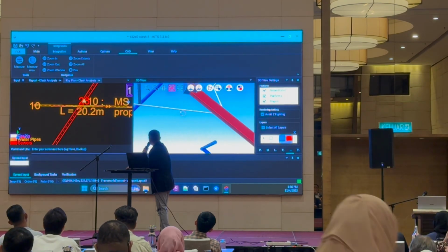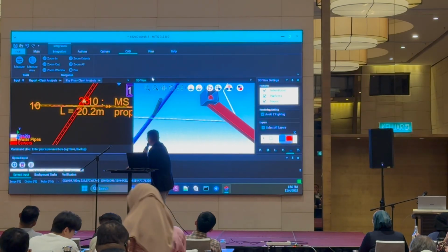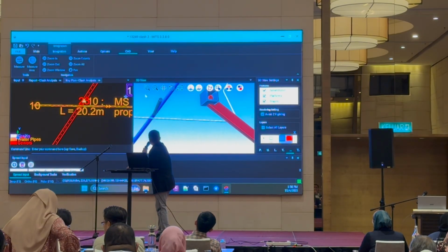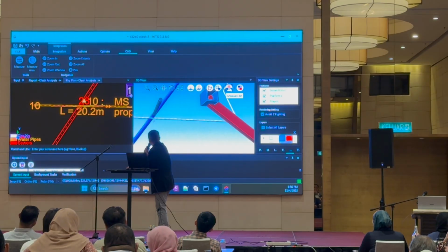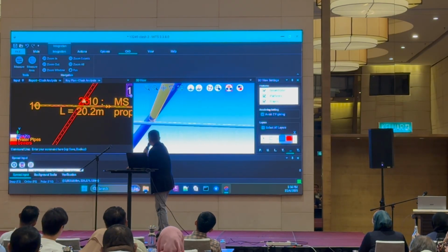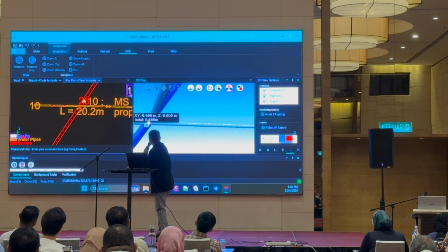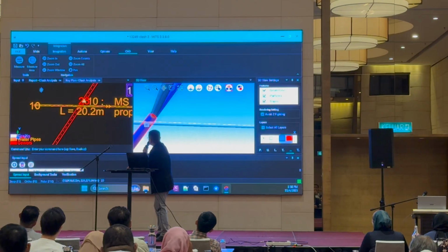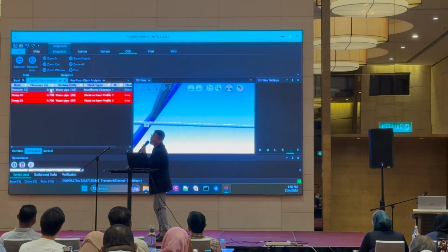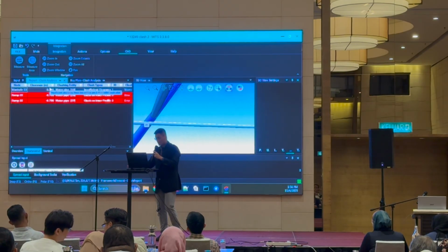Let's try to measure them once again. You can measure in 3D, do the distance measurement in 3D. Go to Measure 3D. Select the manhole and the water pipe. It gives the measurement 0.486, exactly as what we saw here. So this is how we verify that everything is consistent.